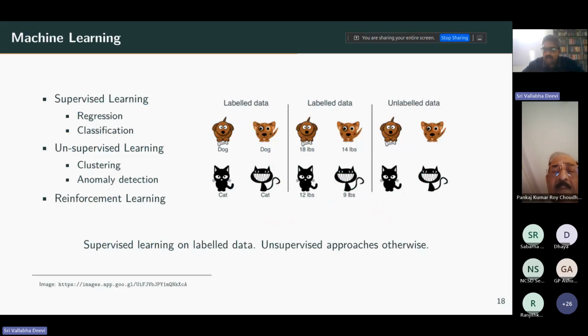A classification model, on the other hand, can tell you whether a particular component is defect free or whether a particular component has a defect. By doing an inspection, you send a scope into the object, take images or take photos. Those photos you pass to a classification model. It will be able to give you an understanding of the defect in the component, and say whether this component is defective or not. Today, some of that is manual. People send in a scope and then the expert monitors it manually. If you want to scale and do more inspections, you can take the help of a model.